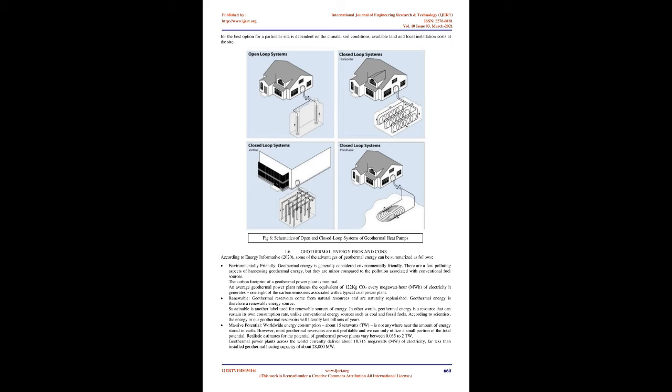Stable. Geothermal energy is a reliable source of energy. We can predict the power output of a geothermal power plant with remarkable accuracy. This is not the case with solar and wind, where weather plays a huge part in power production. Geothermal power plants are therefore excellent for meeting the base load energy demand. Geothermal power plants have a high capacity factor. Actual power output is close to total installed capacity.